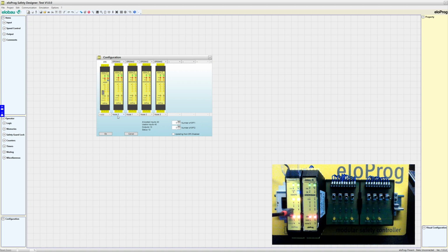And which is very important, you also have to choose additional information for the CPU, for the base module, the nodes, because they all have the same address, which are addressed by the rear side bus. And to address them separately, we need the node number as additional information. We start with node number 0 up to node 3. That's 4 nodes.